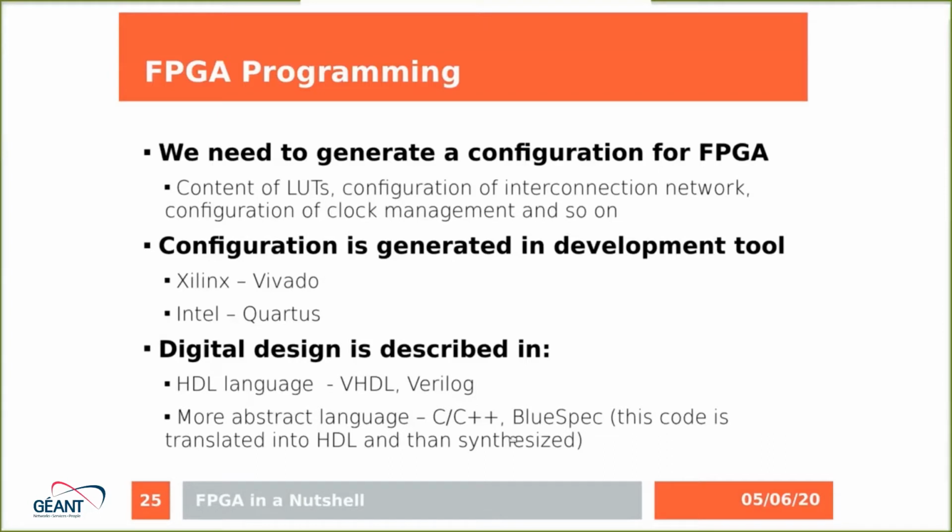I will also show you an example of how the design in BlueSpec looks like and how we can translate it. I have a question here regarding the development tool. For example, if it is Vivado, is it provided when you buy the FPGA card, or is it free to download? Yeah. So in the case of Vivado, you can download it from the Xilinx webpage. But after that, it depends on the FPGA, because if you buy some FPGAs, you need to buy a license to use them inside of Vivado.